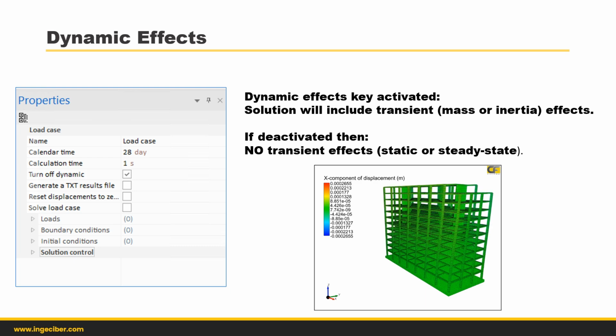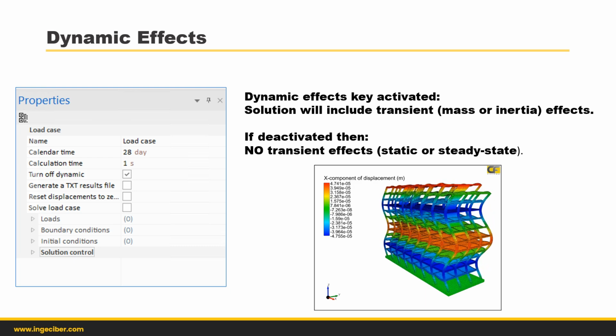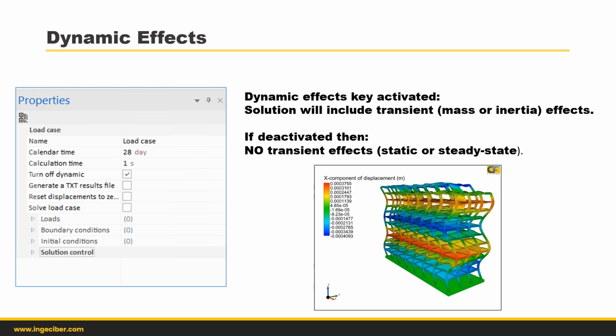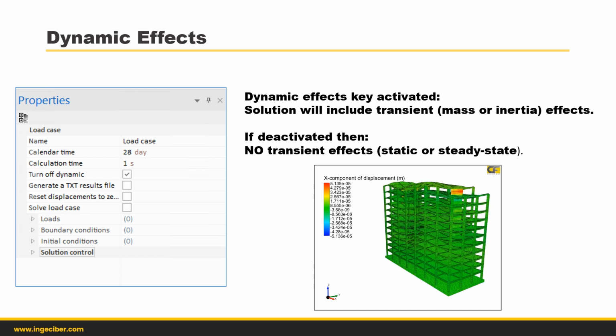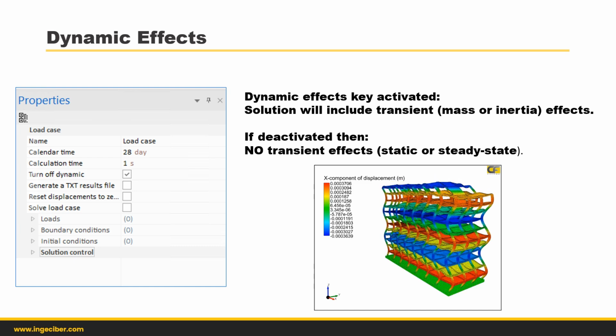This new checkbox indicates whether the selected load case in a transient analysis should use time integration, that is, whether it includes transient dynamic effects, for example, structural inertia, or whether it is a static or steady-state load case.